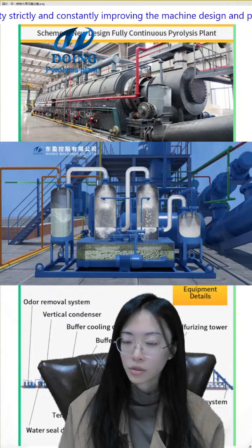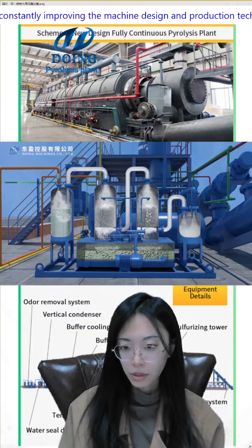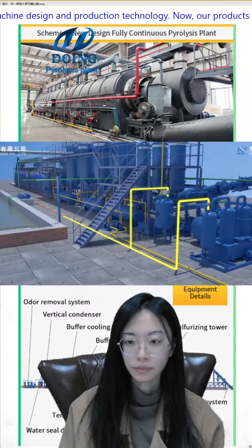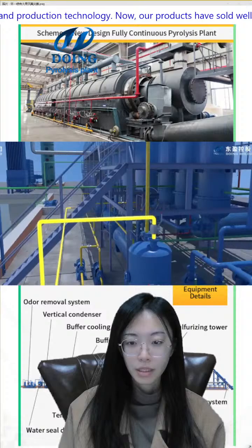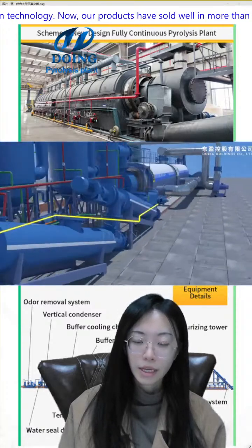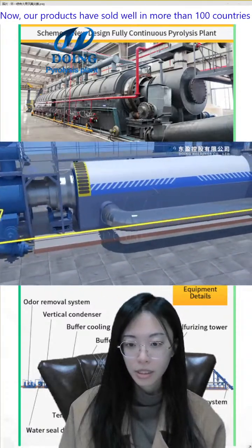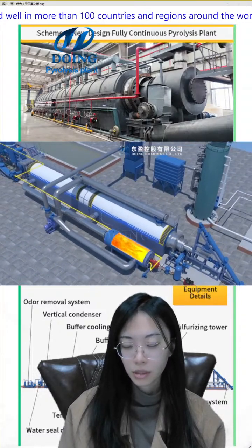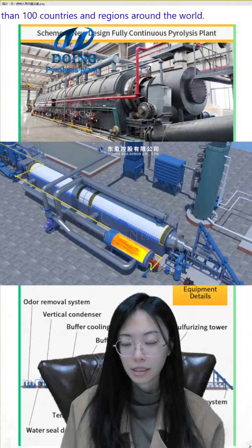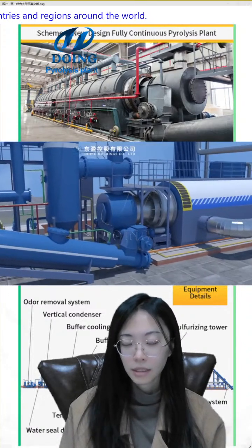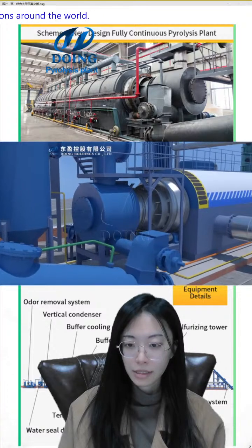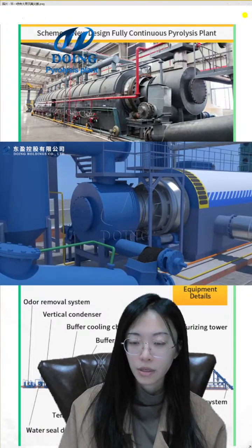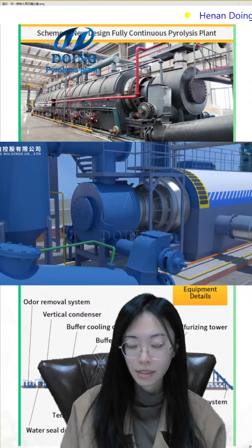And then this is using the spraying tower to spray to remove the sulfur dioxide. Then by using this, we can save our heating energy. In the very beginning, we use extra heating energy like the syngas, the natural gas, flue gas to burn. Then in the later few days, we can use only our tail gas to burn.